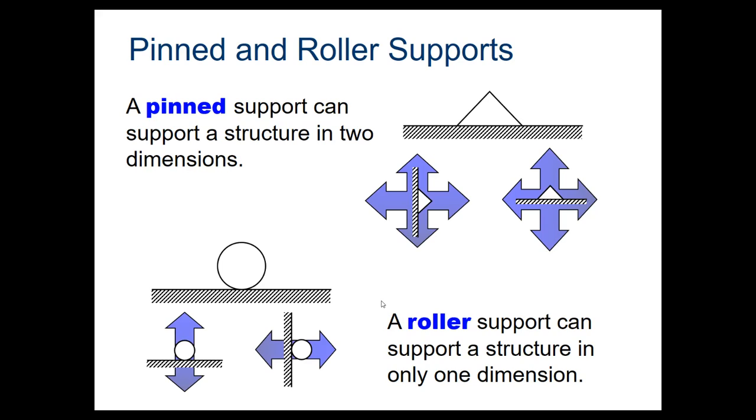And so this is just put there to help prevent your bridge from breaking itself as the temperature changes. So the roller joint is there to support your bridge in one direction only, and then allow it to move in another. And normally it's going to be this way where it's holding the bridge up, but it could certainly be on a vertical surface as well.